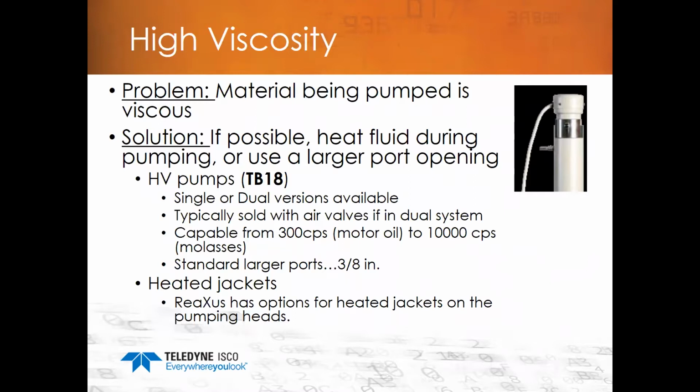But secondarily, what I've seen other customers do and mention to me is they've also put heated jackets on the products themselves to heat the pump, to heat the cylinder, to change the material consistency or the viscosity of the fluid that you're pumping. And that will loosen it up. But in some cases, that could be an issue because the heating of the material could change the consistency or the actual properties of the material, and that can be a problem. So you need to consider that, and that's why we're asking.